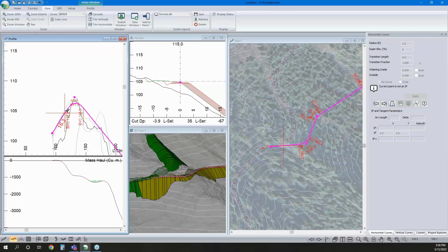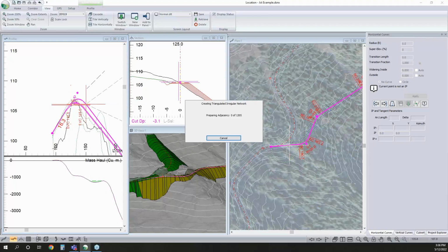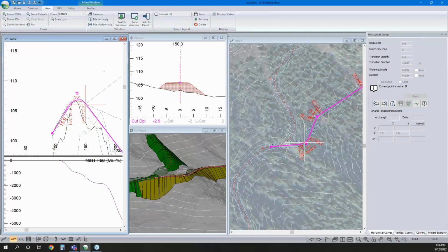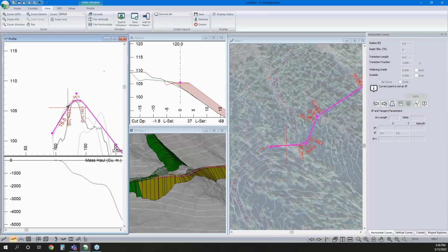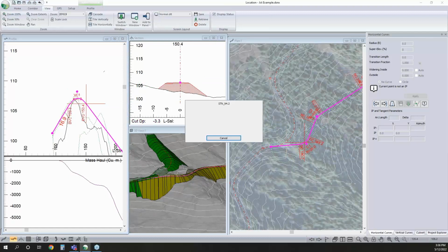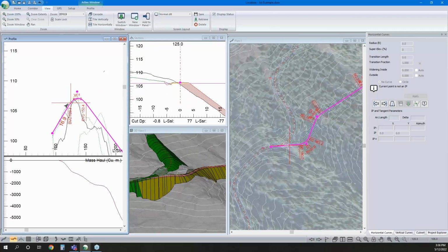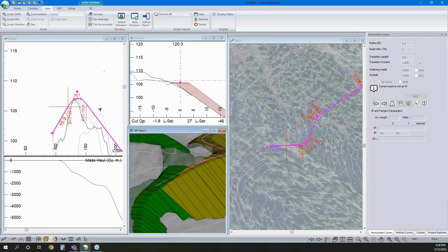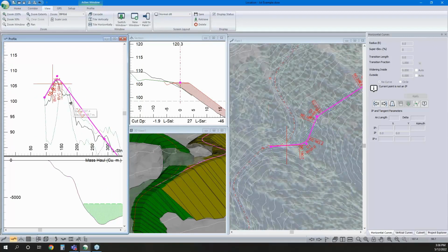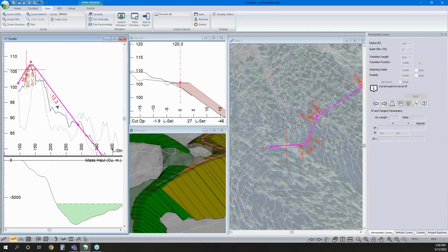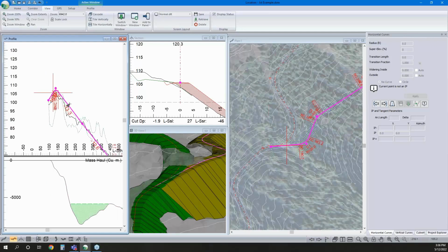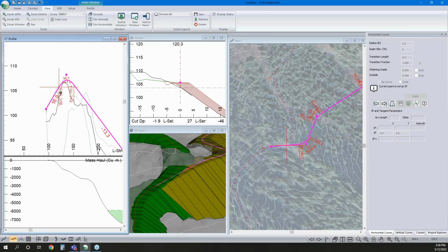I want to keep going out a little further here before we close. I'll go a little higher yet. That's looking pretty good. And I'm steep. It's within my tolerance, so I want to be at an adverse grade of 14 or less. So that works for my case.